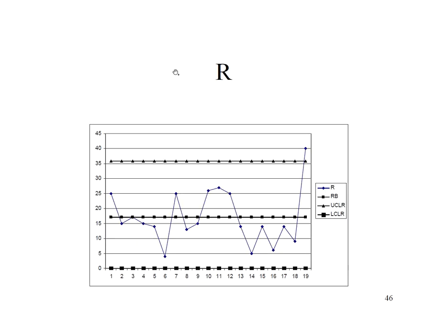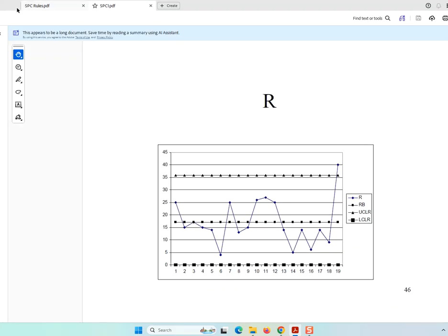All right. Then we did range, which is the range rather than the standard deviation. R-bar is the average of the range. Now, the smallest the range can be is 0. It doesn't go negative. So 0 is the lower limit, right? That's by definition. And then the average range is about 36. And so then you can see how the variation from run to run is going, right? This might be a problem here. Anyway, that's the control chart slides.